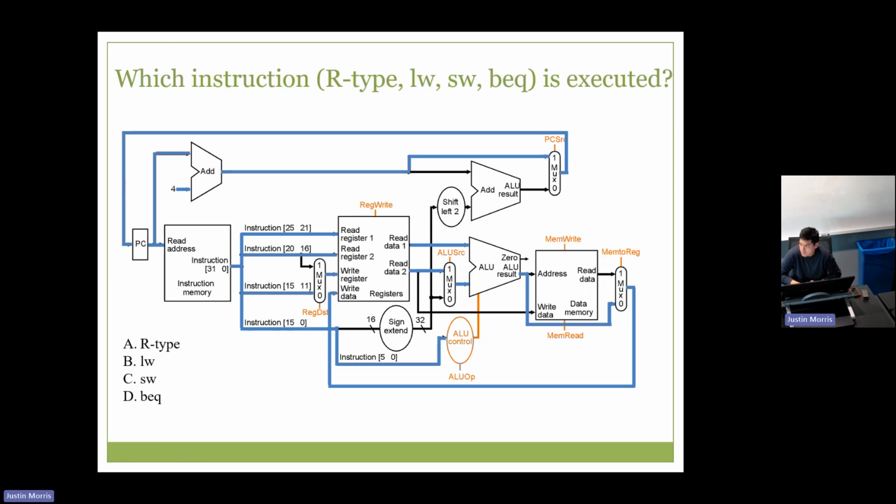Looking up, seeing the PC adder, the only thing that goes through all the way is adding PC by 4, so it increments, and there's no branching or anything going with the memory as well. So nothing's written to memory or taken from memory. And so it's some sort of R type, based on going through that. This is what I saw from the network.